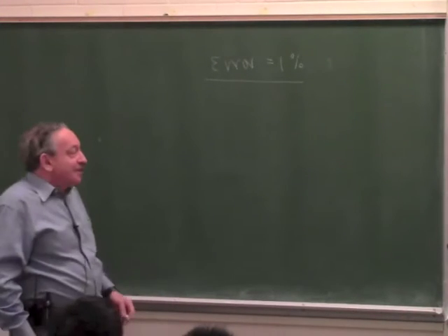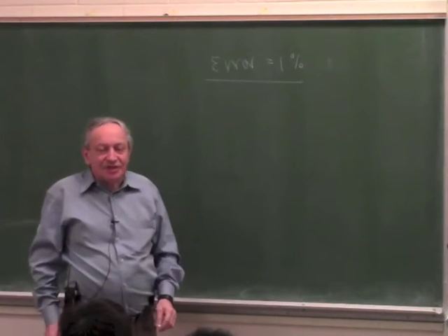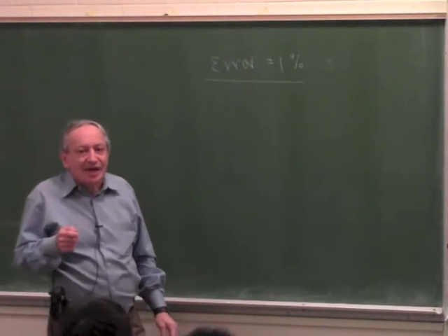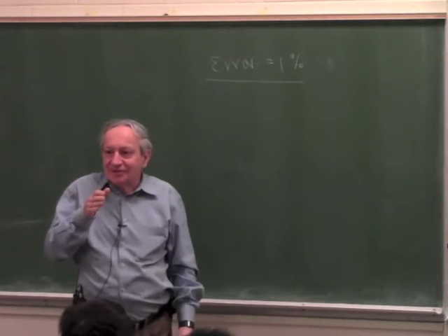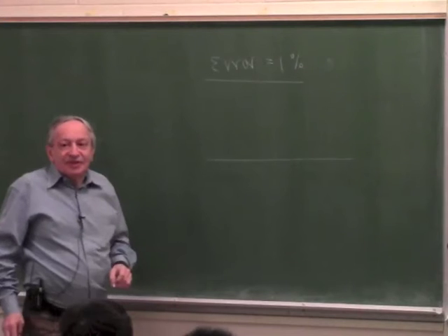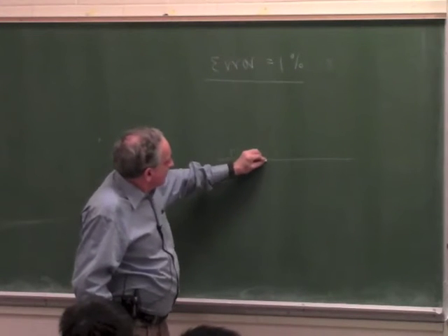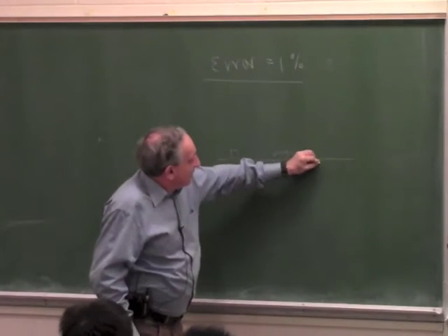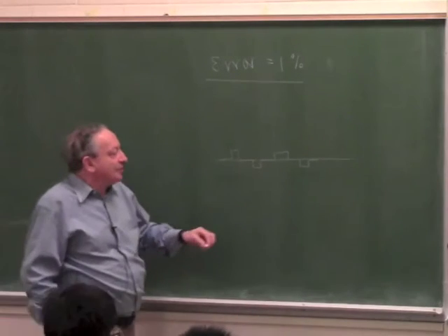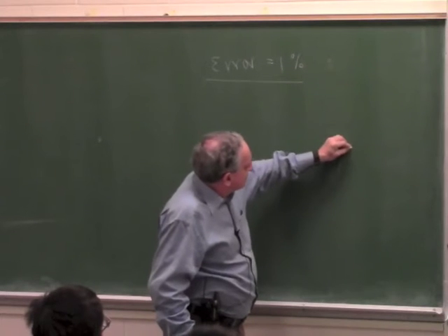But it turns out it's not true. It turns out you need at least 8 bits to achieve that. And the reason is, think of how a servo works. It always hunts around the target. When you have a digital servo, if this is a target, the digital servo will hunt around it. It will go like this. And actually, most of the time, because of delays in the servo loop and so on, it's very common to actually have 2-bit errors.